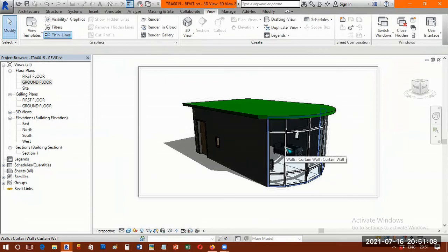Let me check, is anything left out? Camera, external, interior done, shadows done. Extremely well. So in this example, quickly glance at what we have done: we got to know how to set drawing units to mm, how to get a project browser, how to set a plan view, how to set a room size, how to place doors and windows, how to flip the door, how to set that size. Window size, I forgot to tell.